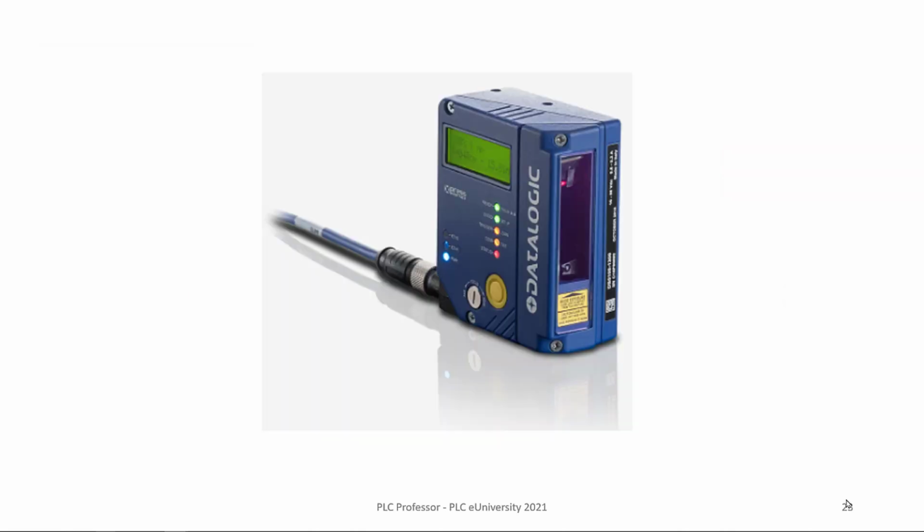These are just images so you can see what they look like. This is a barcode reader. The reason I'm showing you this is our virtual machine has a barcode reader on it. Now, the barcode reader is only there to kind of complete the picture. The only thing we're doing with it is simulating triggering it. Because remember, with our application, the barcode value tells us whether or not that part needs a hole bored in it. If not, then it goes straight on through and out the bottom. If it does, then when it gets to PE2, cylinder 2 pushes it in to get a hole bored in it. So the barcode reader is not highly functional in our application, but here's one anyway.